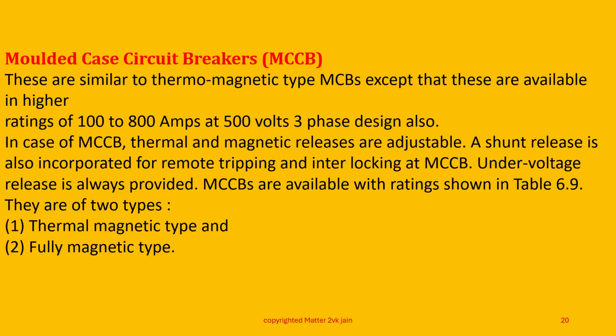MCCBs are available with rating from 63 to 630 amperes, meeting a load of 40 kilowatt to 4000 kilowatt, but normally 2500 kilowatt. These are also of two types, thermal magnetic and fully magnetic.